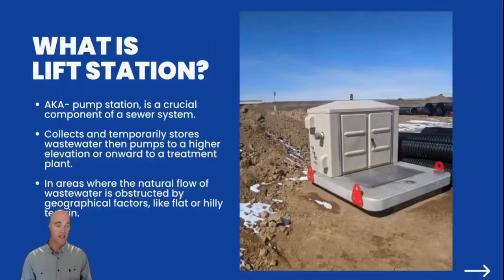So what is a lift station? A lift station, otherwise known as a pump station, depending on who you talk to, is a very critical component of the sewer system or your collection system for your wastewater. What it does is it will collect water and store it within some sort of basin over time. And then once that water is filled up to a certain point, it will then pump that water to a point that's at a higher elevation than where it's at, sometimes going back into your collection system. Sometimes it goes directly into the wastewater treatment plant.